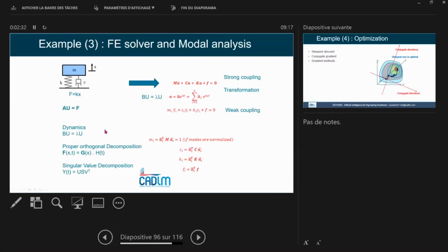But you also remember from modal analysis that we can transform a complex second-order differential equation here into a set of simple and linear equations, decoupled. In the sense, each one of those equations is decoupled. We call this modal analysis, which is much easier to solve. So this is the trick. It's easier to solve this equation because it's diagonal than this one, which is not diagonal. Now, once we do this, we can go back and reconstruct our solutions.